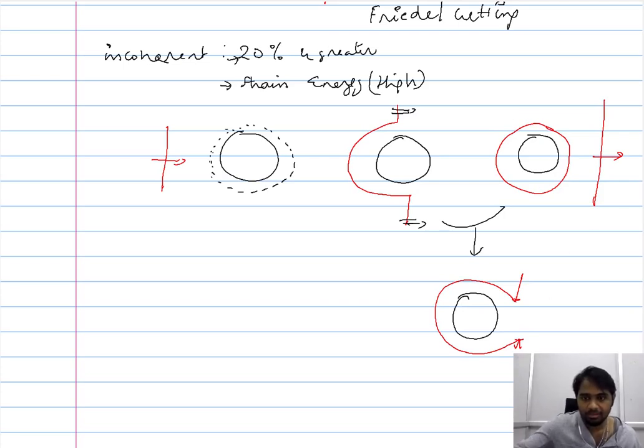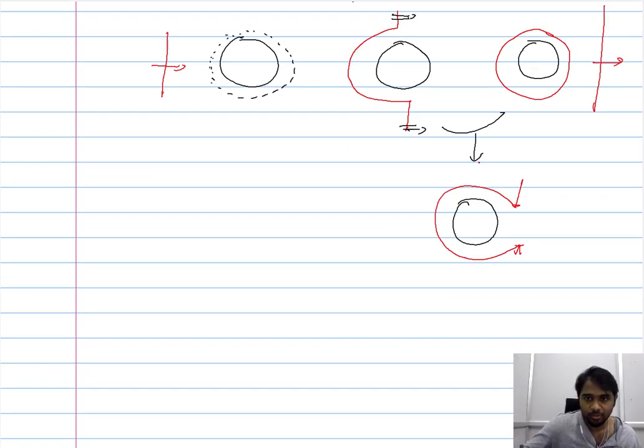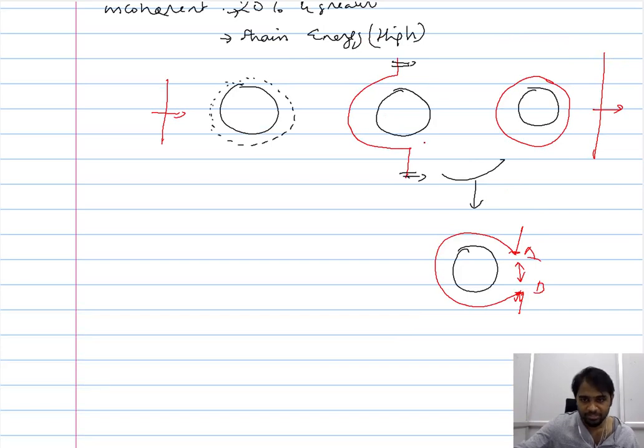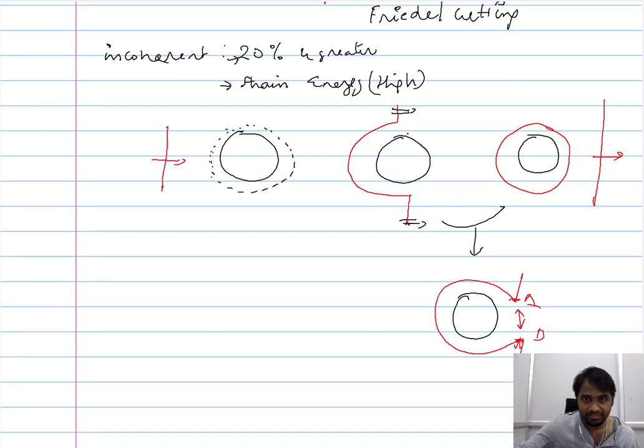And so between these two stages, you have a stage wherein the dislocation is of this form, and as it moves, these two points, this point A and B, come closer, and when they come closer, they annihilate with each other and lead to the detachment. So when your precipitate has an incoherent interface, the dislocation tries to move around it, and it leaves behind a section of the dislocation.